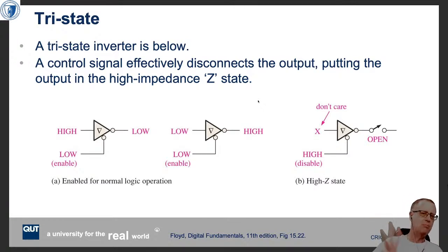Three separate logic states, right, in 363 and what we talked about earlier in this course. 0, 1, and X. Right? X is I don't care. There's a fourth one that I need to introduce you to, which is the Z state or the high impedance state.